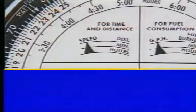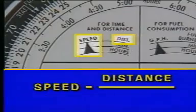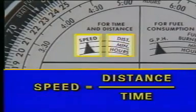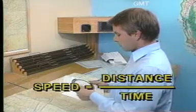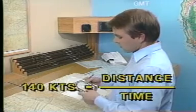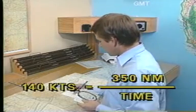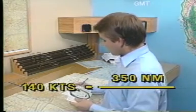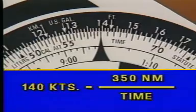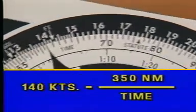If your aircraft speed appears over the index, you will find distance on the A scale and time on the B and C scales. For example, assume you're planning to fly your airplane at 140 knots for a distance of 350 nautical miles. How long will your flight take? First, place the speed index under 14, which is 140 knots, when you mentally delete the 0.